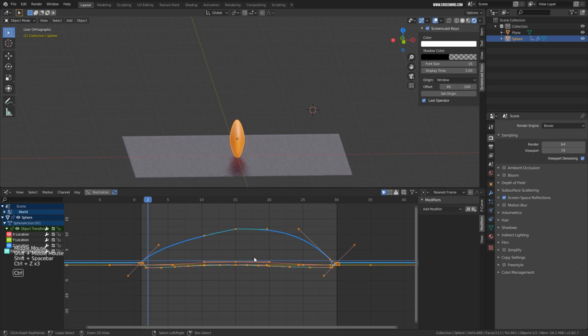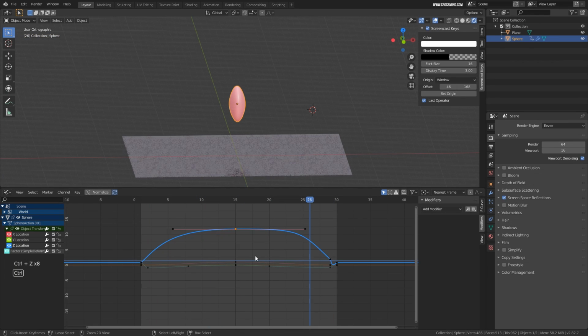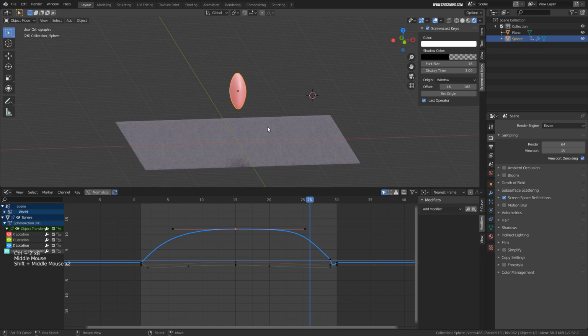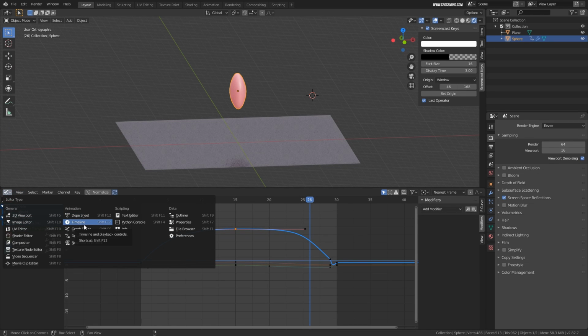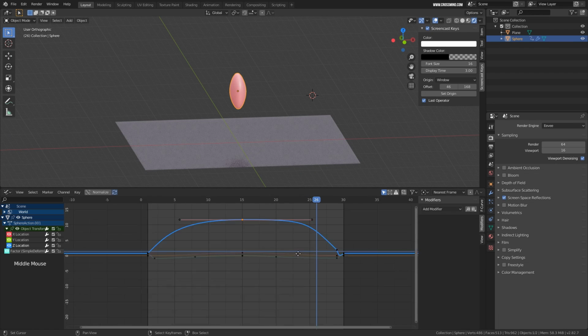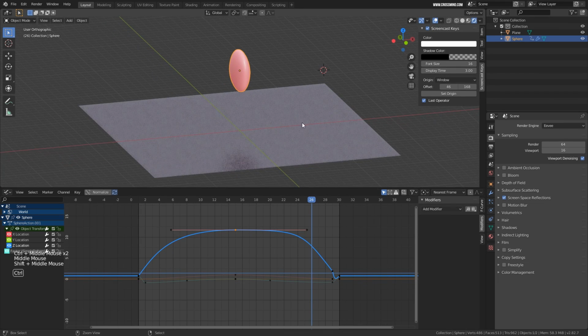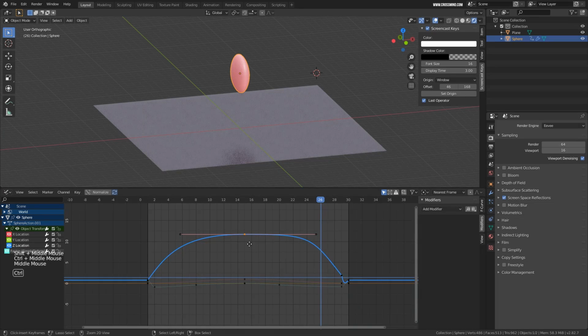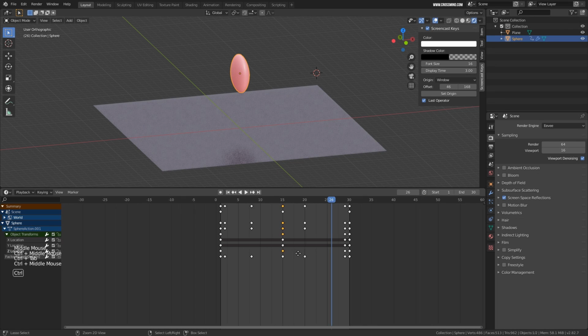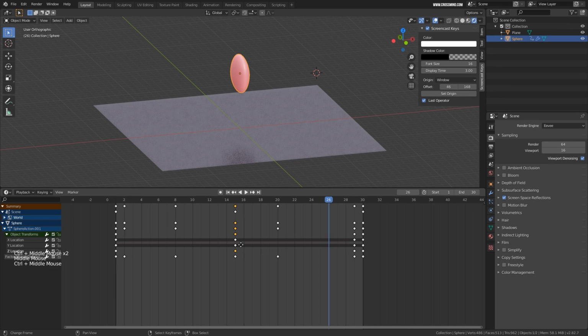Okay, so this is one good thing about Blender. Basically whatever shortcuts and however you work in the 3D viewport, you can navigate in any other editors in a very similar way. Like if you are dealing with the UV coordinates, you can just move, rotate, scale, and adjust the view in a very similar way. Over here I can Ctrl middle click to zoom in and zoom out, or on the timeline, I can Ctrl middle click to zoom in and zoom out.